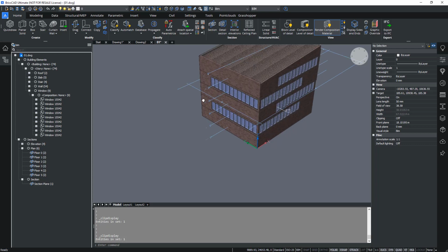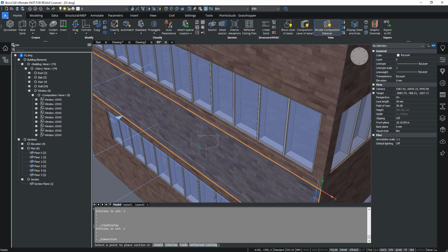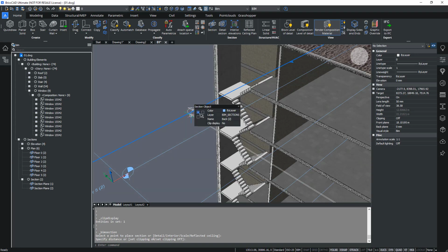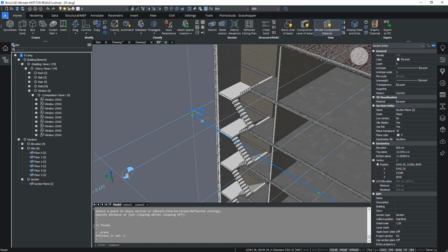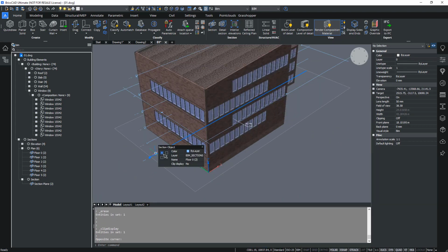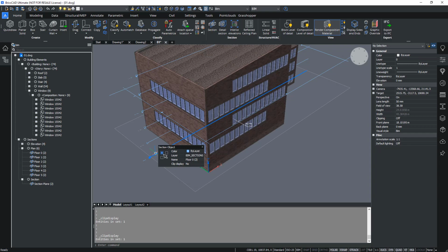The BIM section tracker that is used while creating your section also gives you information about the viewing direction, which is the arrow, and the plane where it will be cut, or which orientation the plane will have for your section. And then you can delete sections by just selecting them and pressing the delete button. You can clip and unclip them by double clicking them.